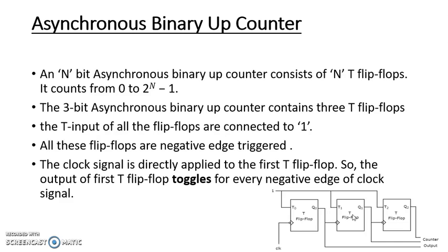If you use a JK flip-flop, we simply short the J and K inputs, and that input is taken as T, which is nothing but the toggle input. Sometimes we may also use D flip-flops as counters. Their construction is different. We will discuss it later. Now in this session we are using T flip-flops as the basic elements of the counter.